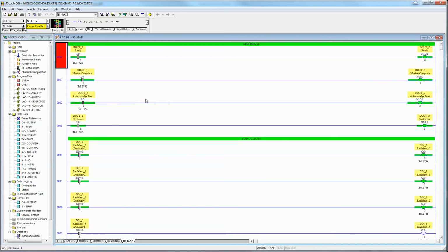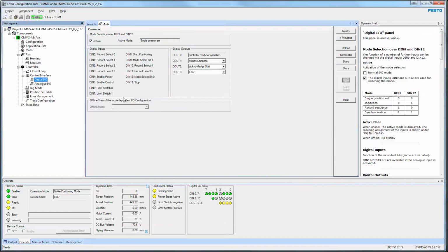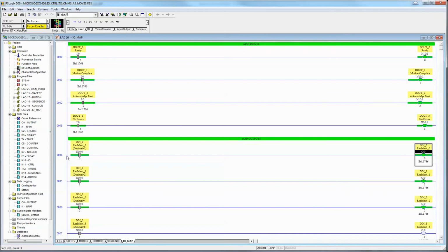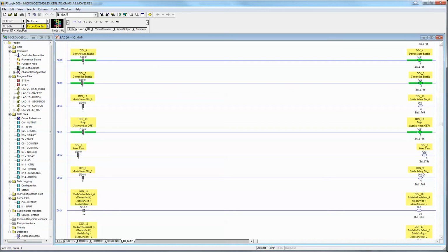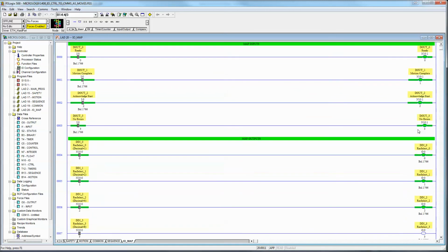Okay. The IO map routine here is made so that the code is a little more portable than normal. This here is the physical IO. Could be any physical IO as far as your wiring goes. These are the bits that are being used throughout the program. So you have your 4 inputs. These again will match the outputs right here. And then I have my map outputs, which are the binary selects and other various things. So these bits over on the right here are the outputs. These will have to be modified so that they match your IO on your PLC.